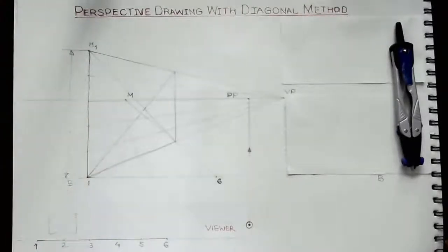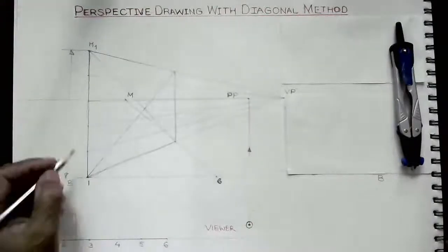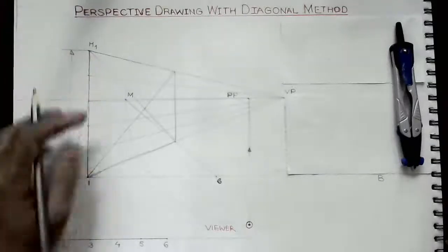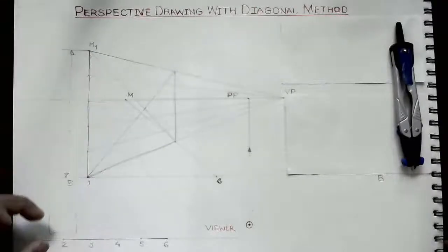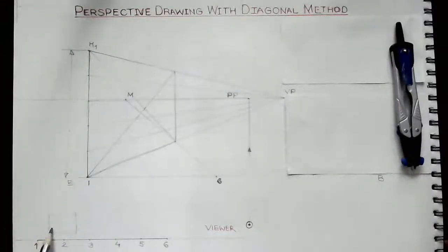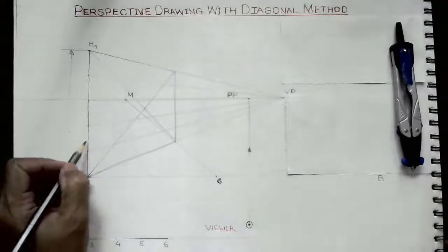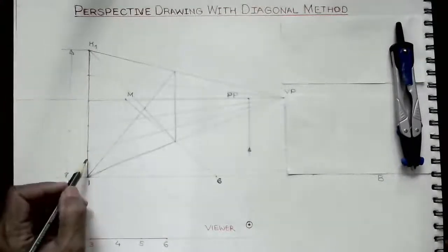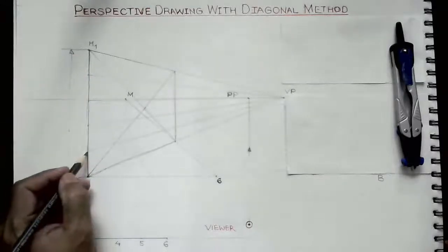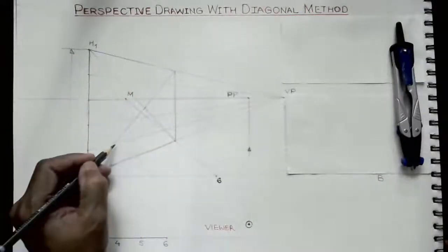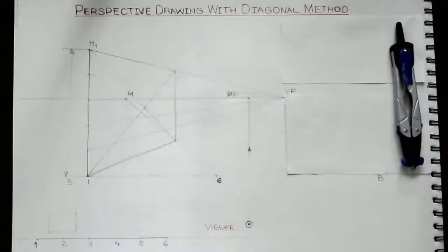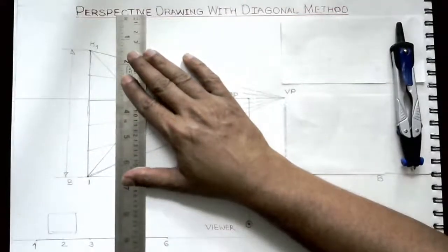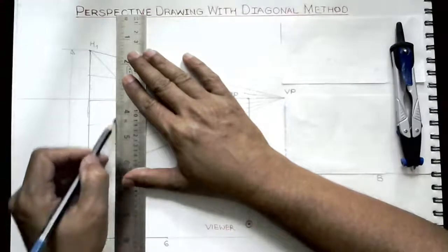Now, once we have these 5 equal parts, we take this height also, and this can be any length. It can be bigger, smaller, or as per what is there here. I have taken the same length for this height. Here it's just a small image which I have shown. It is about 1 inch, 2 inch, 3 inch, 4 inch, 5 inch, and I have divided it and crossed over these lines. Wherever the diagonal is meeting, just draw a simple vertical line like this.